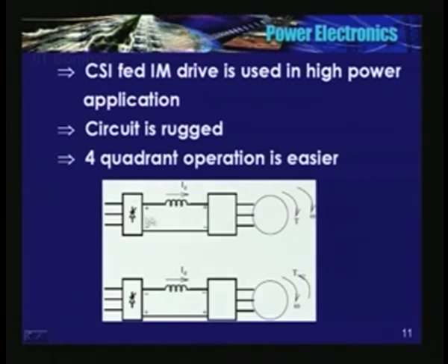I said we need to have a regulated variable voltage here, which you can realize using controlled rectification, and a 3-legged inverter feeding a machine. So at any given time, operation is in the first quadrant. T is also in this direction, omega with plus minus plus minus. Okay.